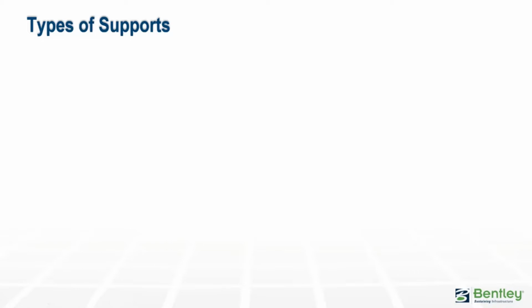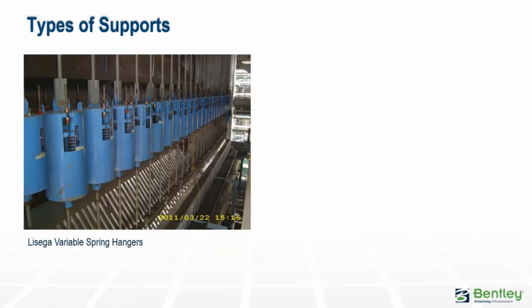So often a compromise is required, and the pipe stress engineer must determine where rigid restraints can be used, which are normally more economic, or where variable spring hangers, constant spring hangers, or snubbers have to be used. A simple resting type of rigid support can also have liftoff that occurs, so sometimes more control is advisable. Pipe operational liftoff means that the restraint is no longer providing the weight support, so it renders the gravity case inaccurate. To carry the weight without affecting the expansion stresses too much, we can use variable spring hangers.